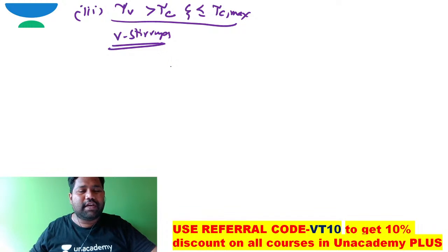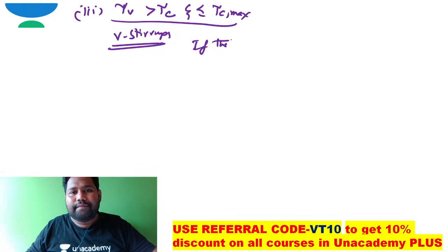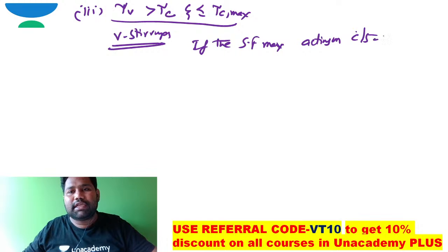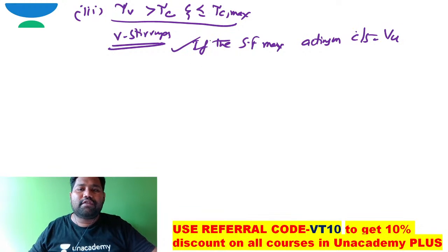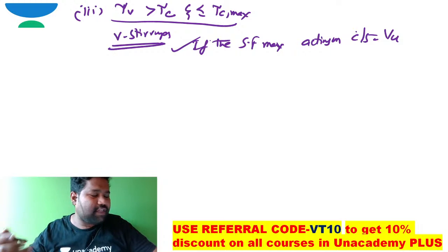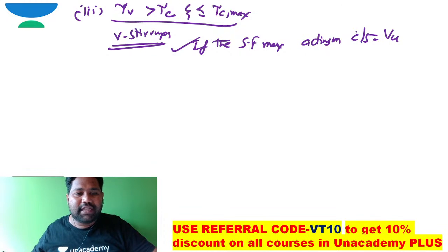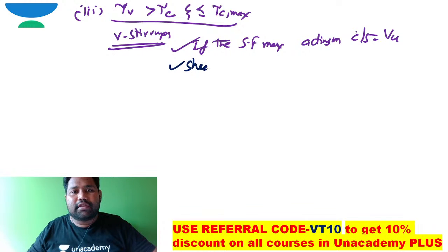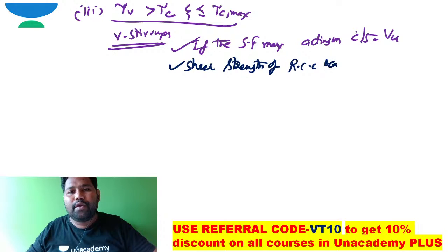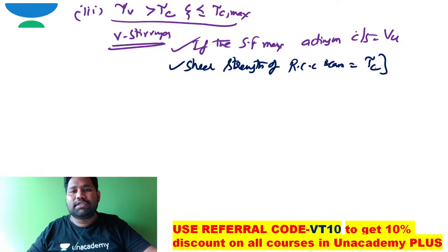Now coming to the design of vertical stirrups, say the question is: if the maximum shear force acting on the cross section is VU, what is the shear strength of this section? How can you write the shear strength of the RCC section? It is shear stress of the RCC, tau c, into the cross-sectional area of the RCC, maybe B into D.